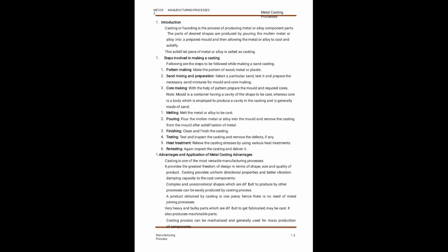For the advantages and applications of the casting process, casting is one of the most important manufacturing processes, providing the greatest freedom of design in terms of shape, size and quality of product. Casting provides uniform directional properties and better vibration damping capability to the cast component. Complex and uneconomical shapes that are difficult to produce by other processes can be easily produced by the casting process.